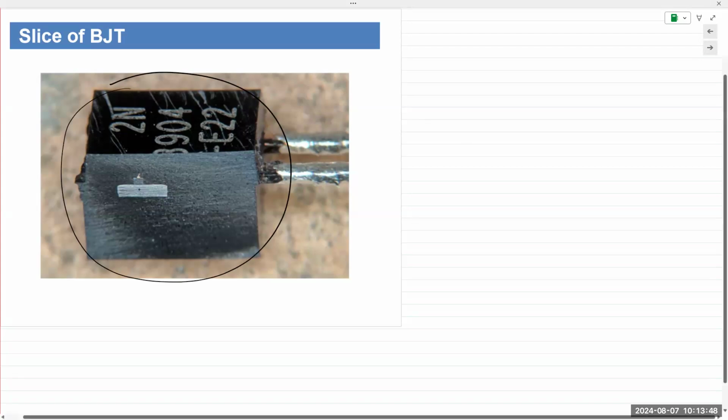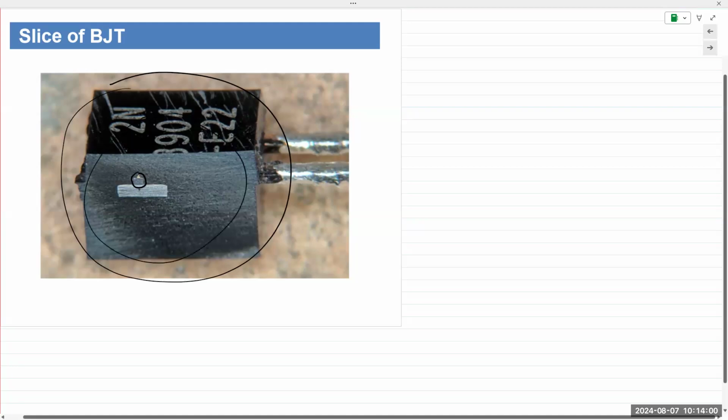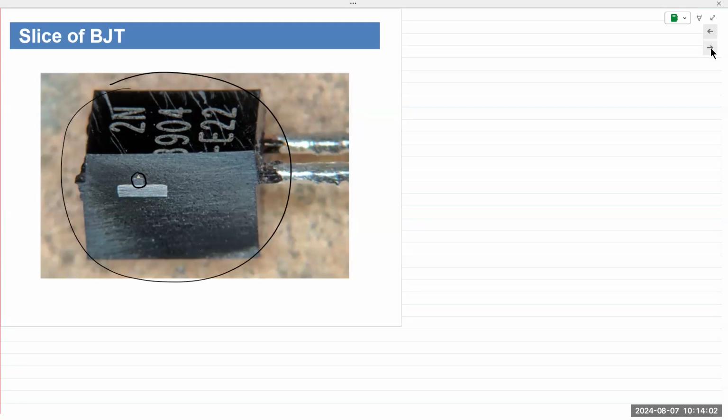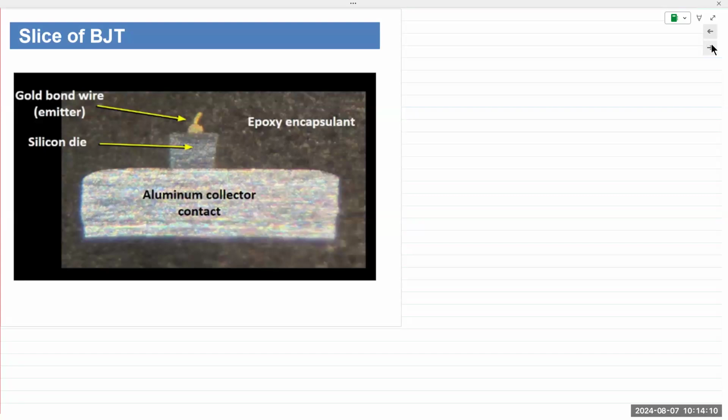Okay. So as I was saying, the actual transistor is right here. It's very tiny. So the transistor itself is very small. The package leads require that the actual package is really big. And that's the case with almost all integrated circuits, all ICs, all microchips. You have a package that seems of a large size compared to the actual device or the actual microchip. The reason is because we have a number of pins, number of connections coming out from those devices.